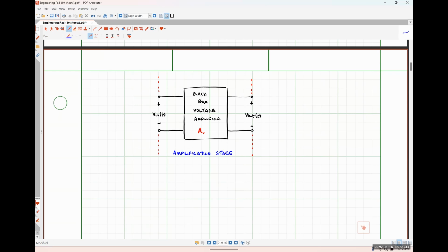Now I'm going to move over to the input side of things. Okay. So that's what's going to be connected to the left to the input terminals of our op amp. And this is going to be the source side of things. I'm choosing to represent this as a practical voltage source. So this could be some resistance RS in series with some signal voltage, which I'm just going to call Vsig as a function of time, like so.